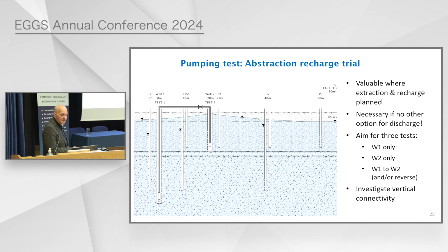So I think you should always be doing an abstraction recharge test where recharge is planned. And again, you need actually to do 3 tests. You need to test each well, probably pumping on it individually, and then do the abstraction recharge.